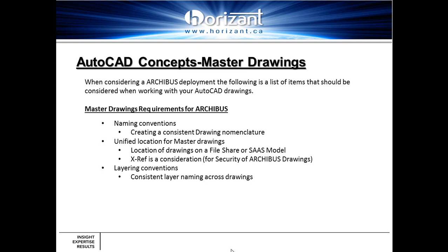Well, when we're dealing with ARCHIBUS and that layering methodology, we want our layers to be consistent from one drawing to the next to the next. The logic behind that is if we ask for a layer to be turned on inside the ARCHIBUS web product, we want all of our drawings to turn on that same layer or control that same layer. So if we start having different drawing layers and nomenclature, then obviously we're not going to have consistency of these reports that are utilizing those drawing layers.